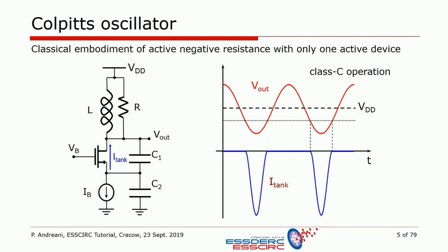The way the oscillator works at steady state is very non-linear, as you can see here. Typically, the current is supplied to the tank with brief and tall current pulses, so they are very harmonic rich. If the tank has a quality factor which is at least reasonably high, all the higher harmonics beyond the fundamental will be filtered off by the tank itself.